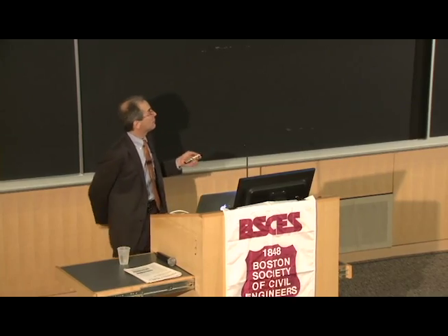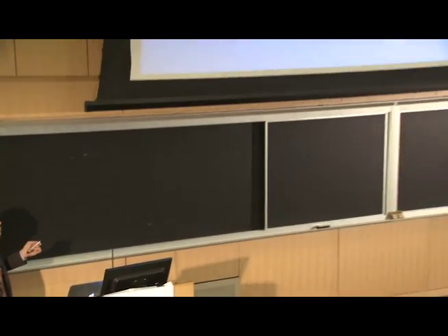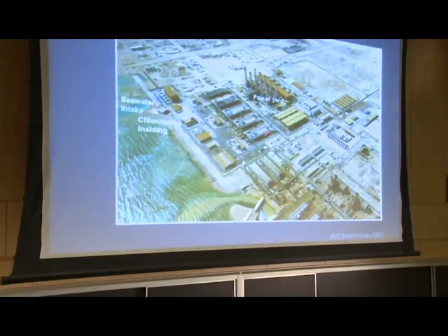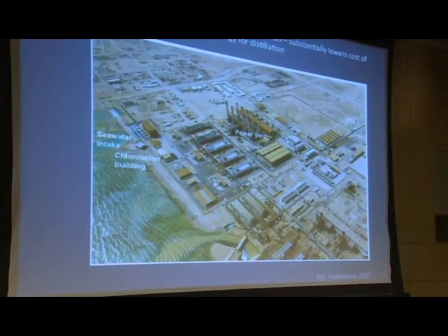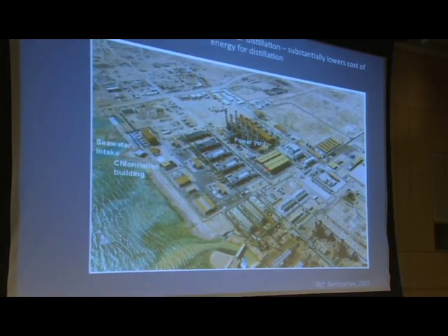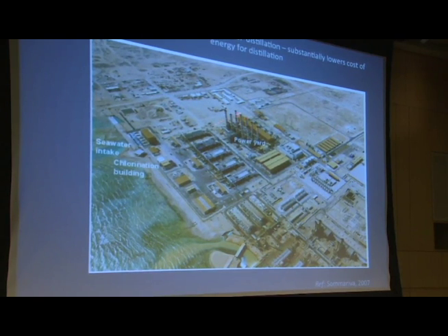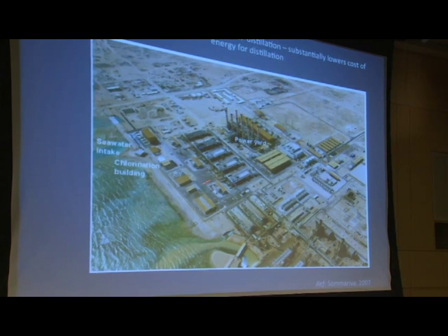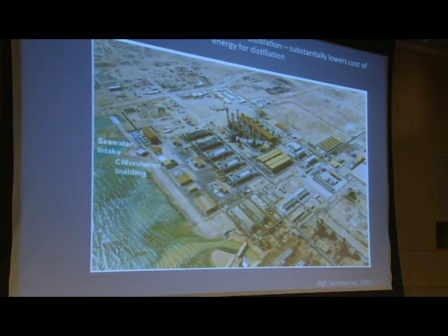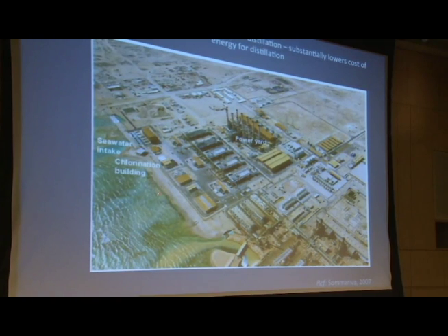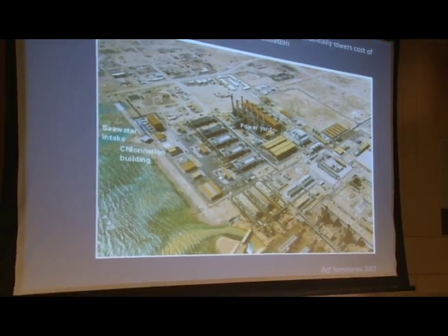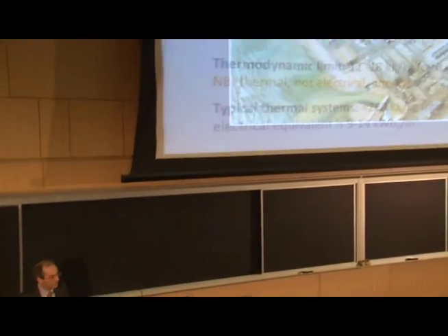This is a representative thermal plant. So this is the multi-stage flash operation that I showed you. Here's one train, another. Behind it is a power plant. And so water is taken into the power plant. It's used as coolant in the condensers. Some of it is also used in the flashing process. Depending on how this system is designed, the water that leaves the plant, the brine leaving, might be blended with some of the coolant from the condensers to dilute it before it hits the ocean.